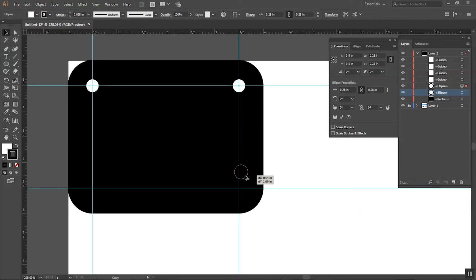So this is duplicate when I hold down Alt. And when I move, you'll notice I can move randomly, and it usually applies. You can also hold down Shift, and that will lock you into an orthogonal world, so it's either 45 degrees or 90 degrees. You'll notice these little pink, sort of lilac purple lines popping up. They're guides just helping you align to various elements. So if you pay attention to them, you can usually get a good alignment of everything.